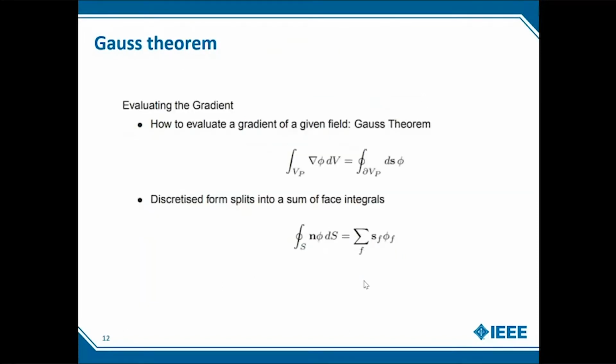One thing to remember before talking about the finite volume method is this particular theorem from calculus, known as the Gauss theorem. Suppose phi that you can see here is your main equation. For example, if you have a temperature governing equation or a heat governing equation, your temperature is the unknown that you're solving for, so phi represents temperature. If you have a momentum equation, then velocity is what you're solving for, so phi is the velocity. So phi over here is the property that you're solving for.